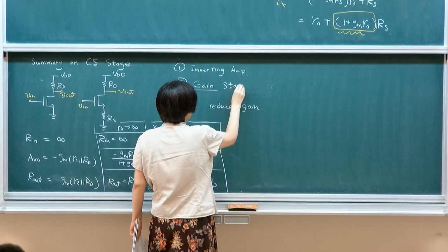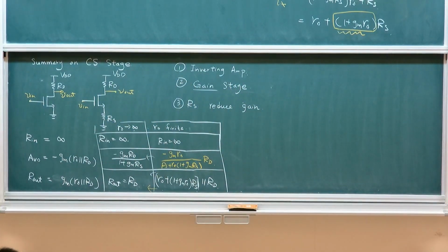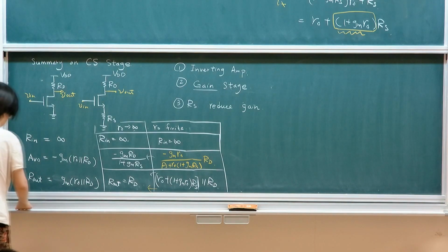It is typically referred to as the gain stage. If you go in and look at most of the MOSFET operational amplifier stages, they have multiple stages. The stage which will provide maximum gain is typically done by having a common source stage, or a common emitter stage if it's a bipolar version. So typically this structure is used as the most simple gain stage. Okay?